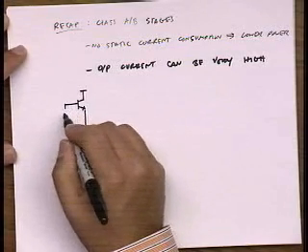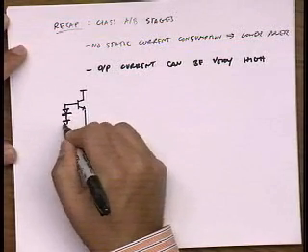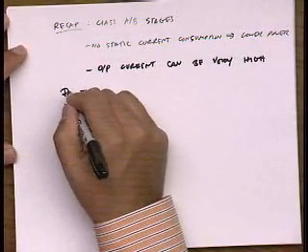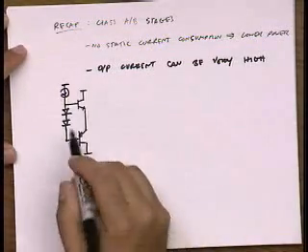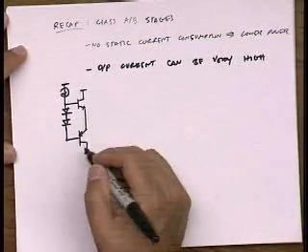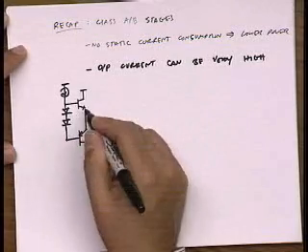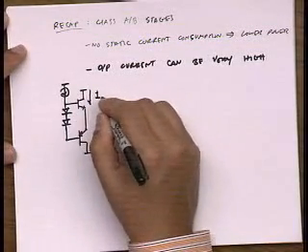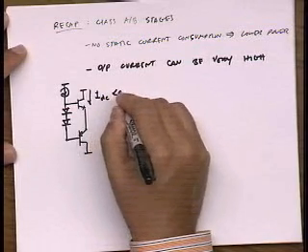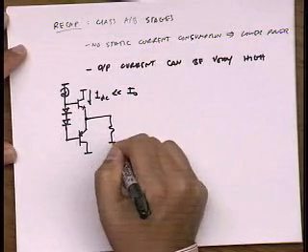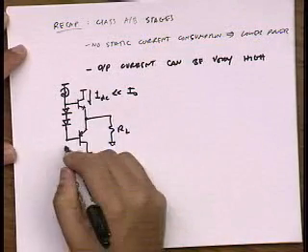We biased these with enough voltage so that there is a trickle of current flowing through to put these VBEs close to on, so both are on. But the current, let's say IDC, is going to be much less than the output current you need to drive your load.